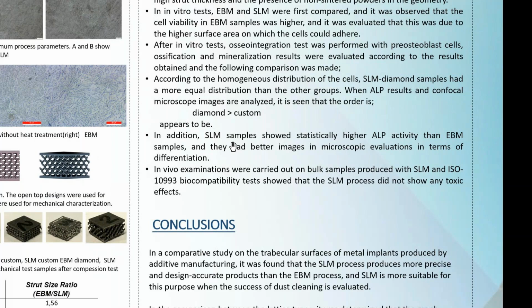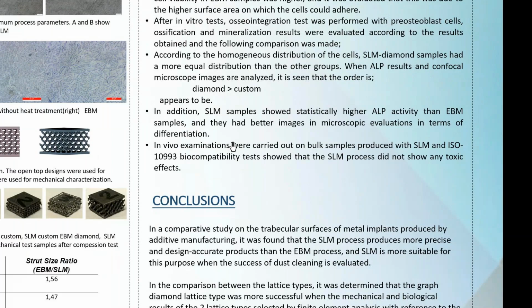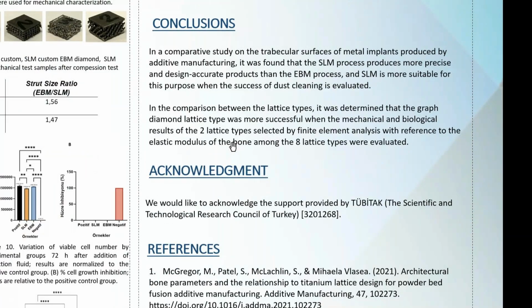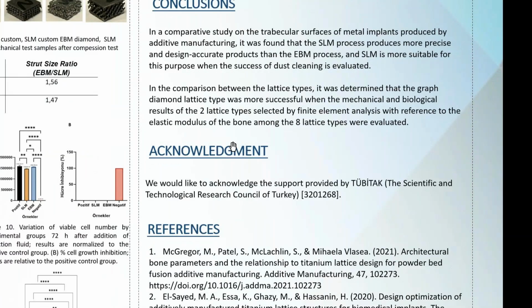In conclusion, we conducted a comparative study on the trabecular surfaces of metal implants produced by additive manufacturing, and we found that the SLM process produces more precise and design-accurate products than the EBM process, and SLM is more suitable for this purpose when the success of dust cleaning is evaluated.